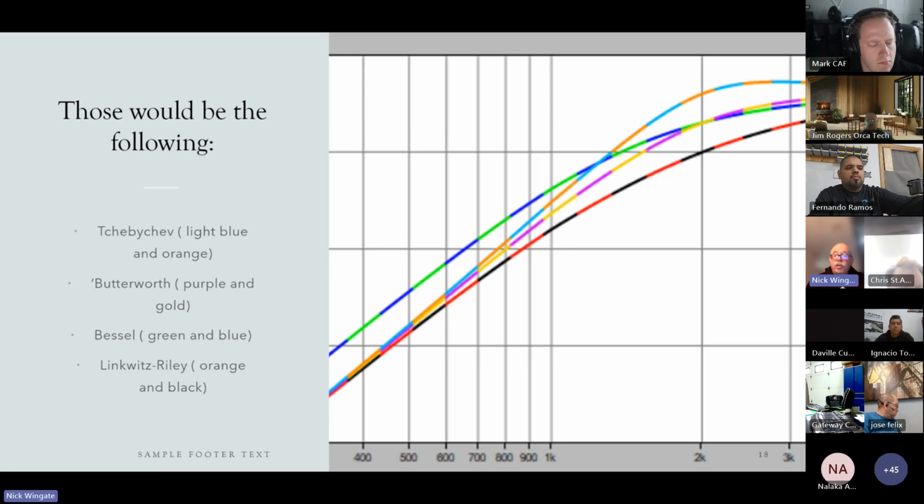It's there if you need it, because if you're at the crossover point and you're using, let's say, a Butterworth high pass and a Butterworth low pass, and they sum together and you get this great big huge nasty dip and you can't get rid of it, chances are it's a phase shift. You might try the Chebyshev because of this boost that you see right here. It might fix it. And I encourage you to play around with these. Get in the car, fire the system up, go listen to it, and actually just listen. That's how I learned. Just listen to how these things sound, and you'll get an idea as to what these things do and how they work.